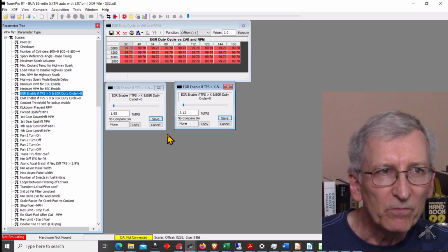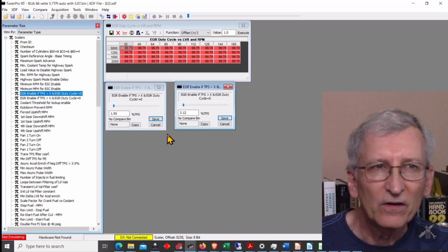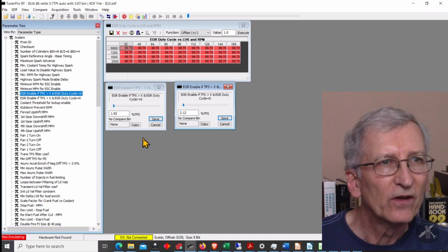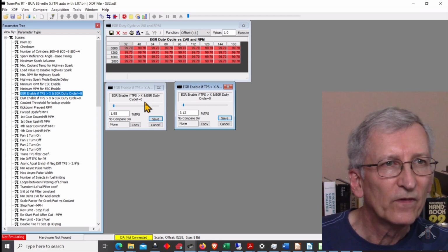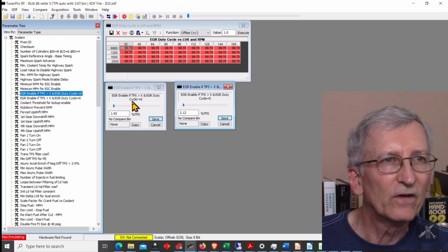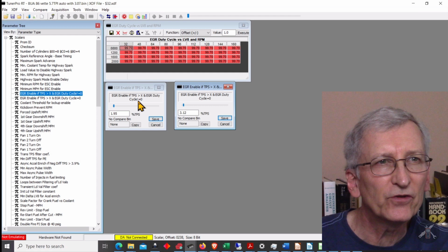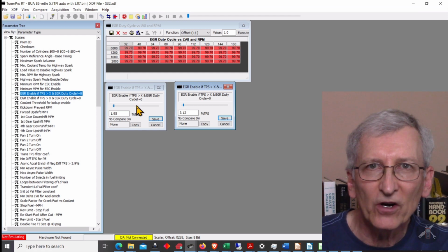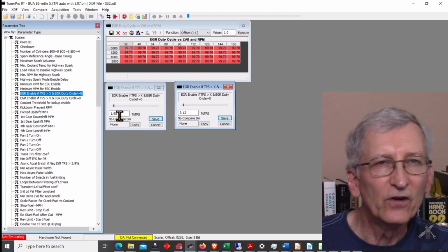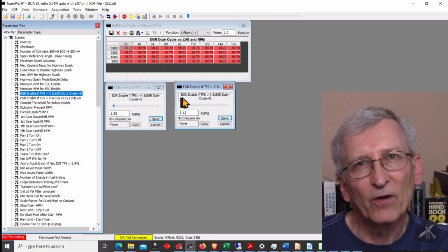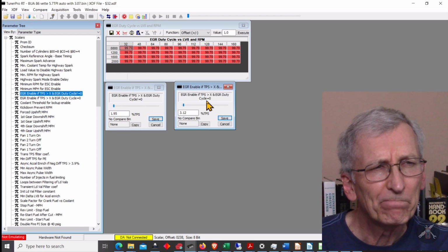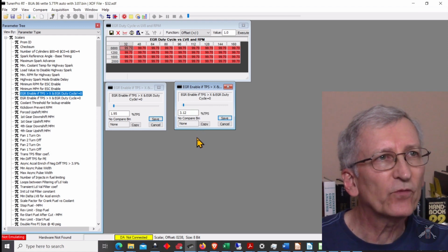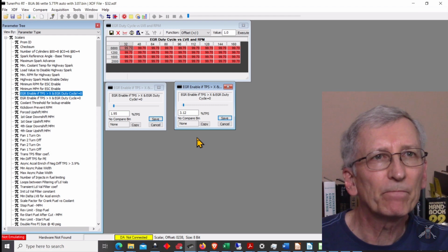So somebody built into this software a branch that's special, that says, under these conditions, I have a duty cycle with an exclamation point variable. I want the TPS to be lower. I want the EGR to come in sooner. And then here's one where I want it to come in a little bit later. Scratching my head a little bit, but that's what an '86 Corvette looks like.